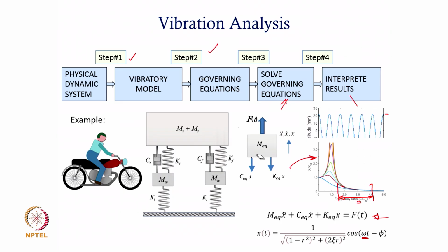As you can see here, instead of a single mass, I can get a mass of the chassis as a separate one. But if this wheel is going to have a significant mass, and if I want to investigate this vibration in a more accurate way, for high speed traveling automobiles, I would definitely like to model the wheel itself like a mass.